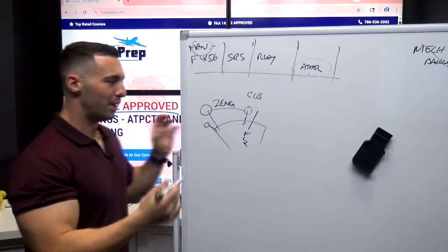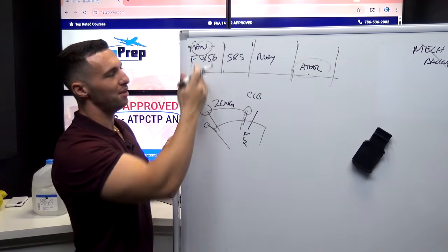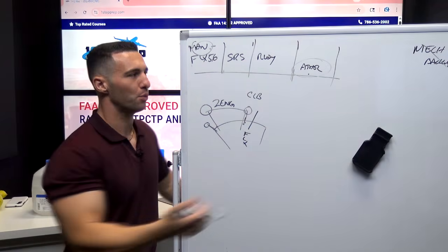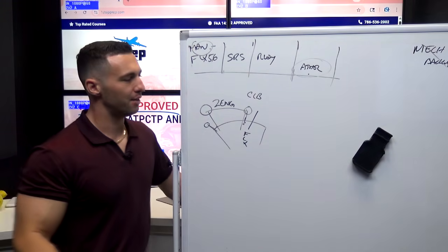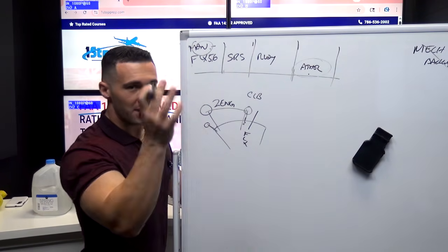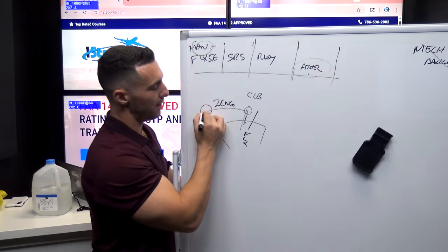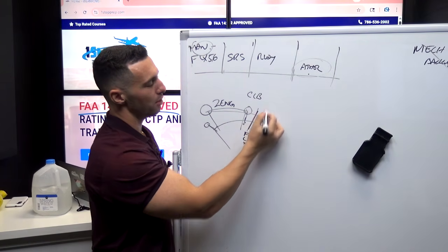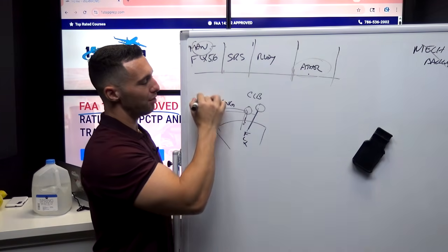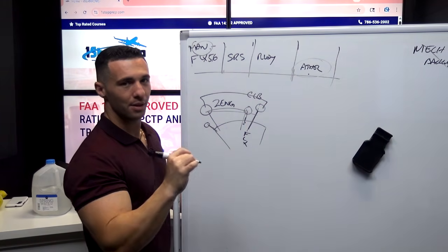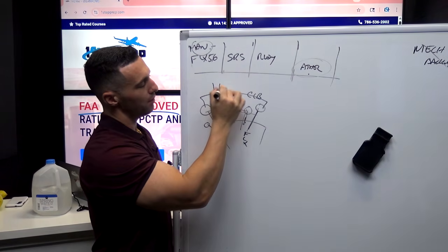So then we get to the thrust reduction, we bring it back, we go to the climb position, and all of a sudden we see THR CLB, and auto thrust turns to white, and the white very much means now it's active. Now, all this will tie back into what I'm going to say with alpha floor in a second. If I am single engine, then technically my active range goes up a little bit more to the flex MCT position, right? So for 1 engine, the active range is just above idle up to and including flex MCT.